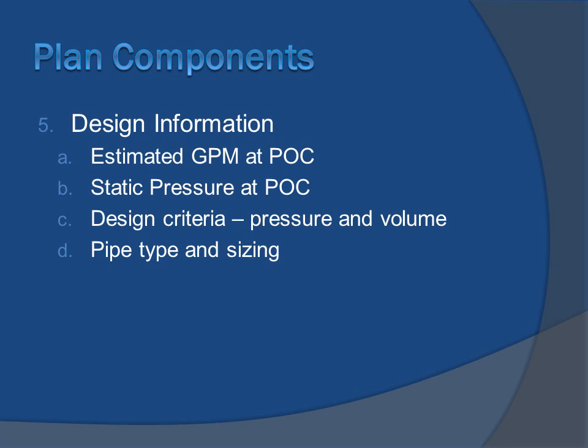When I was in college, we had our irrigation classes. We sized the pipe down to the T. We got knocked off on our plans if we could have sized it down to 3/4 inch. Nobody does that. You see a truck, it's got all 1-inch pipe on it, and bigger if you're on a commercial site. But you're not going to start buying, well, we need some 1/2-inch pipe for 40 feet on this job, and then 60 feet of 3/4 inch. Is it for pressure? Is that why? Yeah, you reduce it to save that pressure.